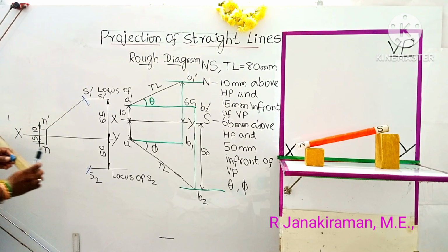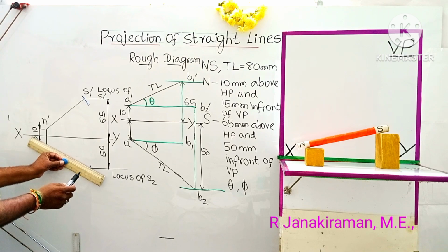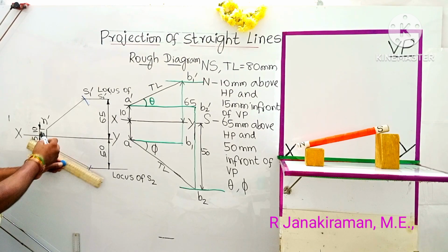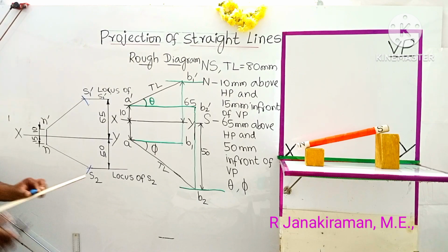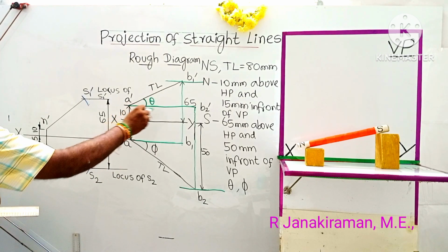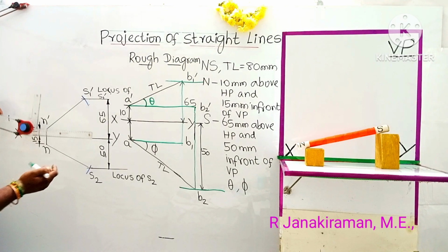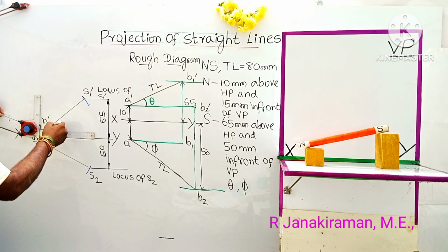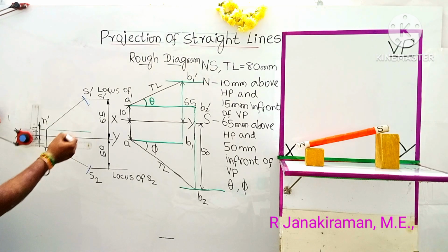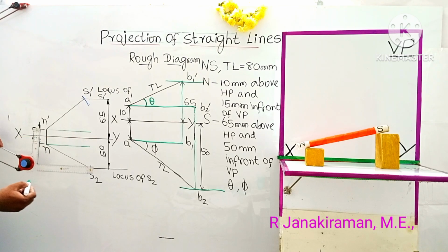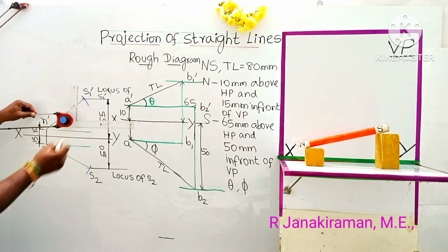By 2H pencil. Understand? Then you draw this green color horizontal line, using the longer scale of your drafter with a 2H pencil like this. Similarly, another locus line at point N. Okay. Then you draw a vertical projector.